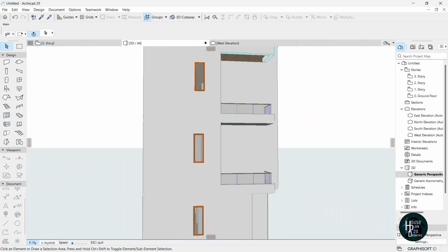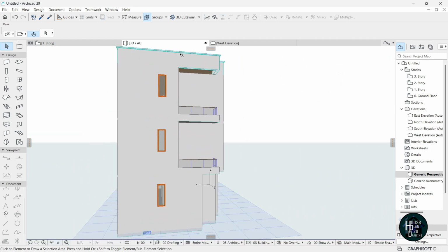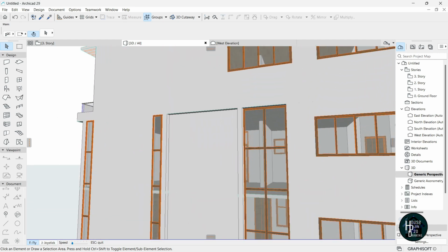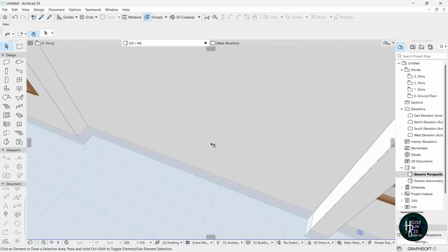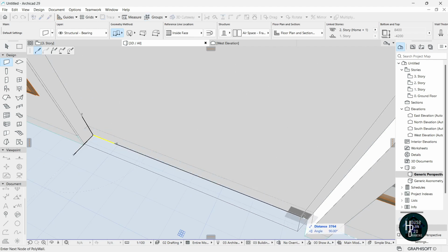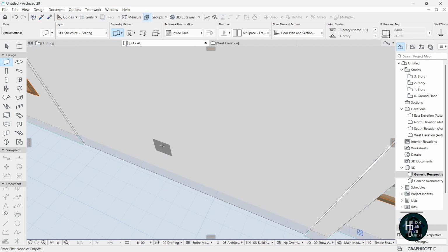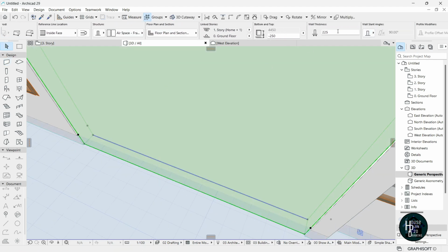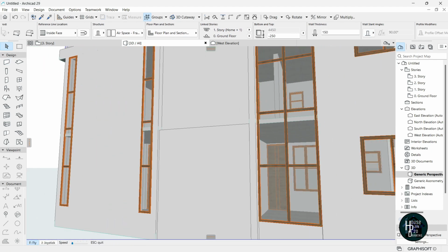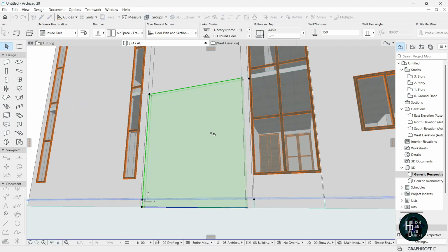We're going to be modeling just this side here, there's a shape here, and then we also need to do a brick design here. So what I did for this is just something simple. You can hold Alt, select this wall, click this, stretch it like this, and then double click the side. Okay, select this, make sure this one is around 150, click enter. Okay, so if you move up, you should have something like this.